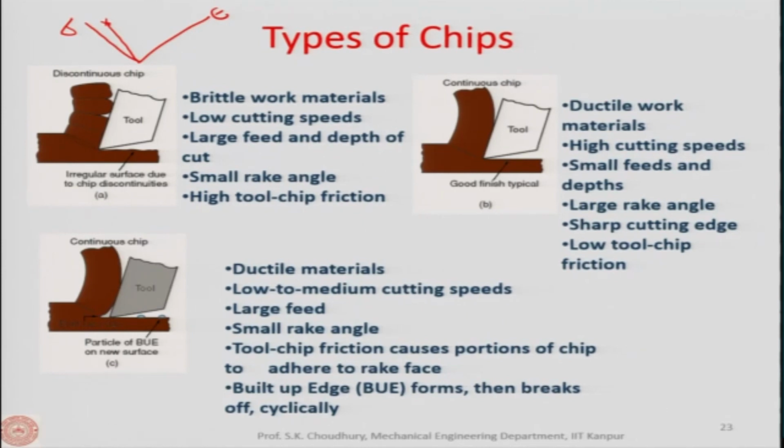Because it is a very high pressure and very high temperature, and the pressure is maximum at the tool tip, similarly, at that temperature and pressure, a very small layer from the rake face of the tool will also be removed, because of the high strain rate of deformation, high pressure, high temperature, at a certain level of cutting speed.